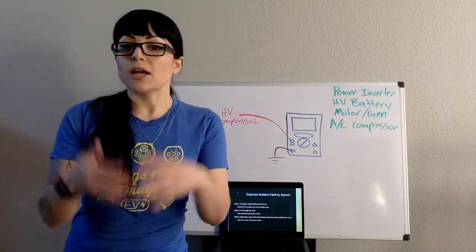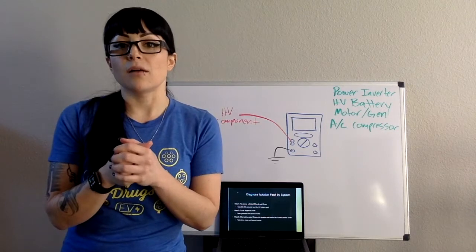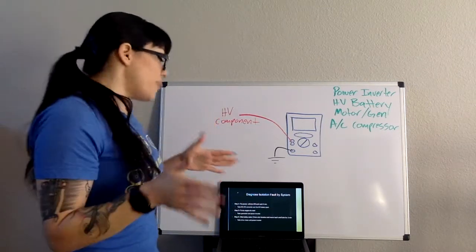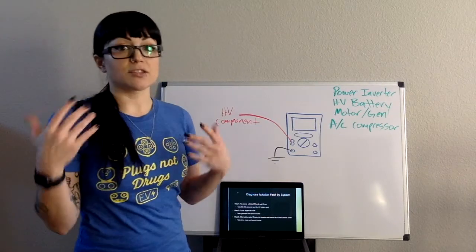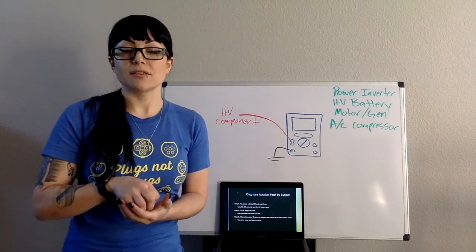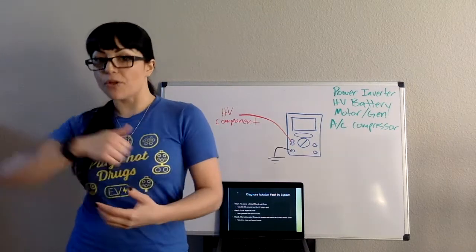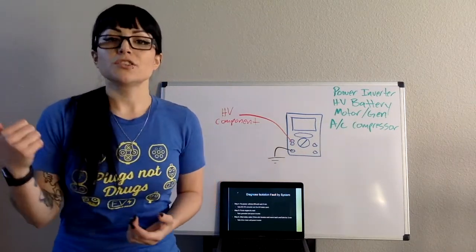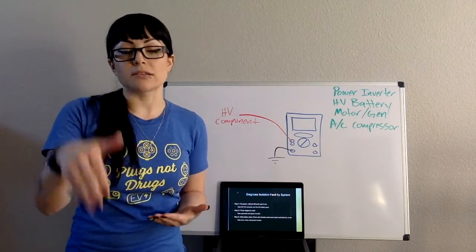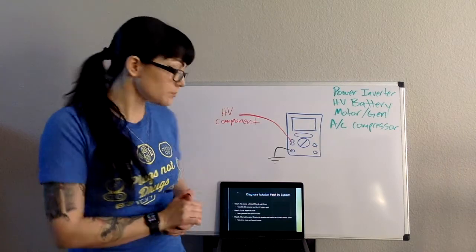If you turn the engine on, and again, it's a 2-minute deal, we're going to let that engine run for 2 minutes. What this does is test the generator, because that's the one that generally generates from the engine running, which will then feed the battery pack, right? So if I have a fault in my generator, the engine running will cause that fault to turn on.